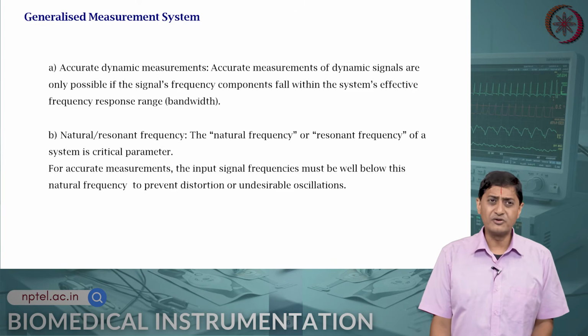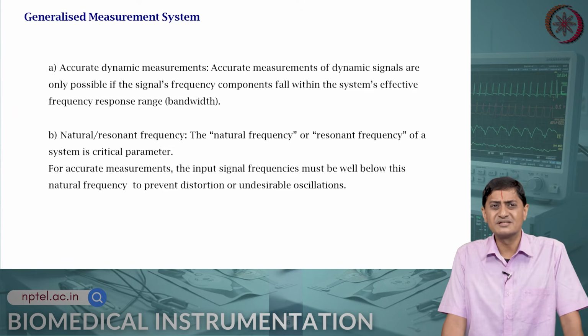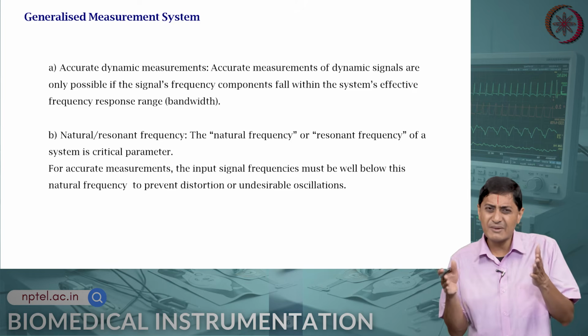And then you have accurate dynamic measurements. So, accurate measurements of dynamic signals are only possible if the frequency components fall within the system's effective frequency response range, that is, within the bandwidth of the system.